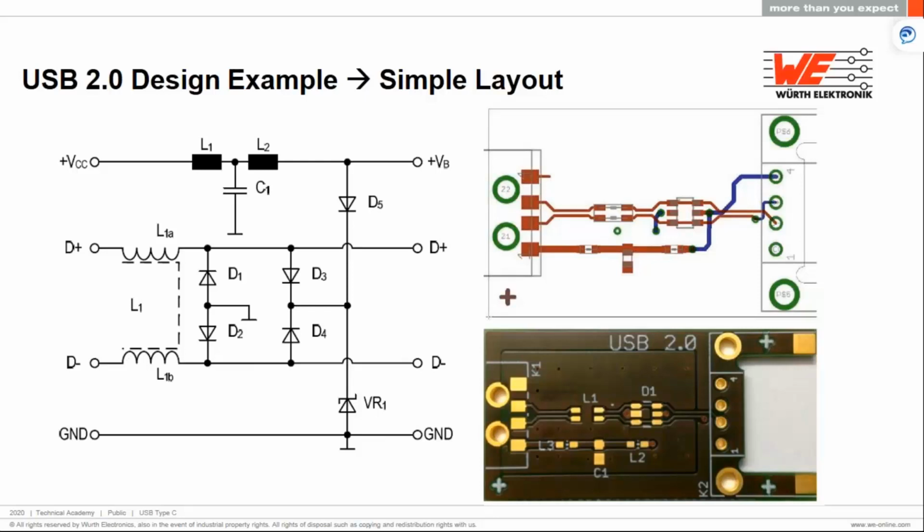So usually, USB has a differential impedance of 90 ohms, and with all the routings that are marked here, the system has a little bit of difficulty to maintain this impedance of 90 ohms. Luckily, with USB 2.0, even 480 megabits is low enough to guarantee the function, and it mostly works very well with this type of slightly bad design. But when it comes to USB 3.0, and when we have more speed, these designs are not valid anymore. At high speed, the data loss becomes very high for such circuits, and that is why we need more efficient filter design around them.